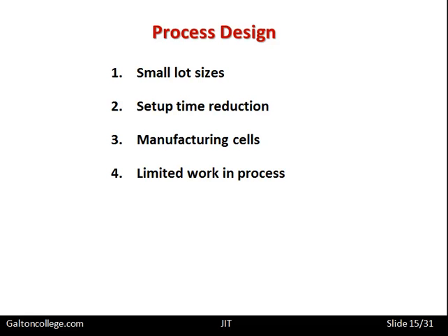There is very limited work in progress with JIT. The work in progress, theoretically there shouldn't be any. The idea is that if JIT was working 100% and set up perfectly, then the components would move from one area of production into the next smoothly. There would be no waiting time and hence no work in progress.